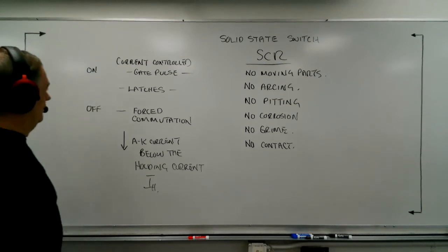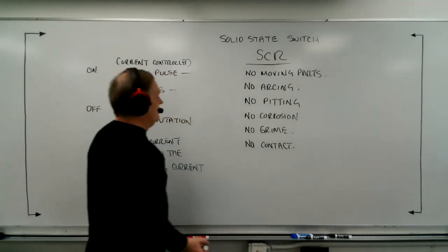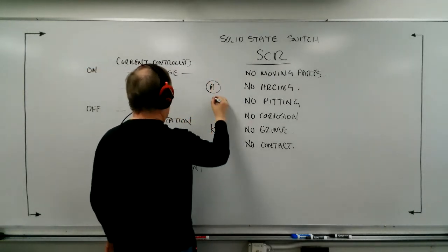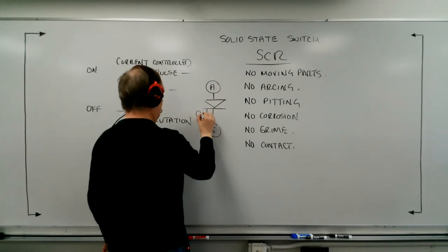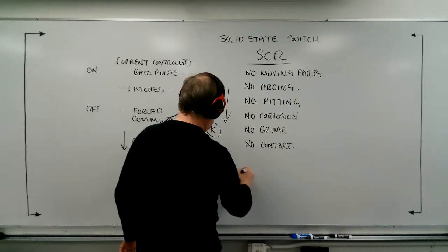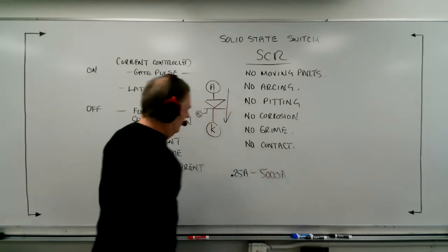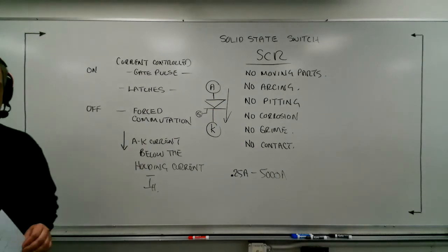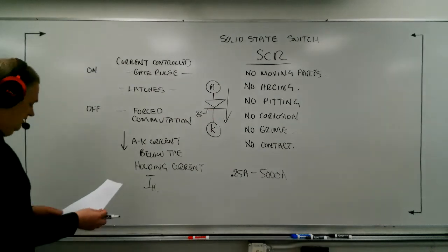Now, I just want to restate the current for these, the typical A to K current through the SCR. A to K, there's your main current path, anode, cathode, there's your gate over there. This current basically ranges between about 1/4 of an amp to sometimes over 5,000 amps, okay? So lots and lots of current. Now, obviously, these are going to be enormous once they get up into the thousands of amps, but it's pretty impressive to see how small even a 40 amp SCR actually is.